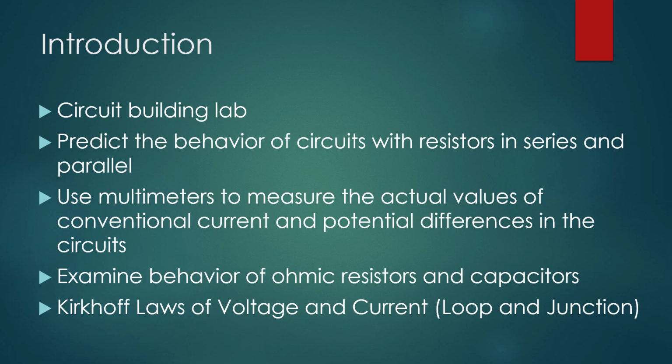A little bit of an introduction. This lab was a purely experimental lab, with no coding aspect. It was about building circuits and using the equations we have in class, specifically around the change in potential across different circuit elements and Kirchhoff's laws to predict the behavior of circuits with resistors in series and resistors in parallel, and then using multimeters to measure the actual values of conventional current and potential differences in the circuits, and then examining how the behavior of the ohmic resistors and capacitors is affected. Using Kirchhoff's laws of voltage and current, we can do math to find experimental values for these different quantities.